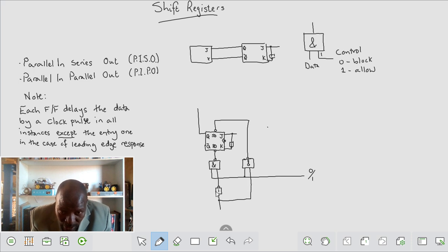That's why we have an inverter for the one. If we want to reset, that becomes a 1, and that becomes a 0. And this one is blocked already, because remember, the moment you put a 0 on a NAND, you are ignoring the other input. So with a 0, that one becomes a 1, nothing happens. With that one there, it becomes a 1.